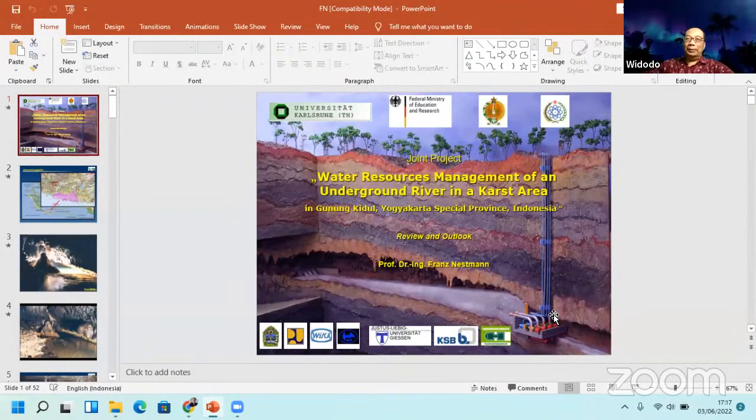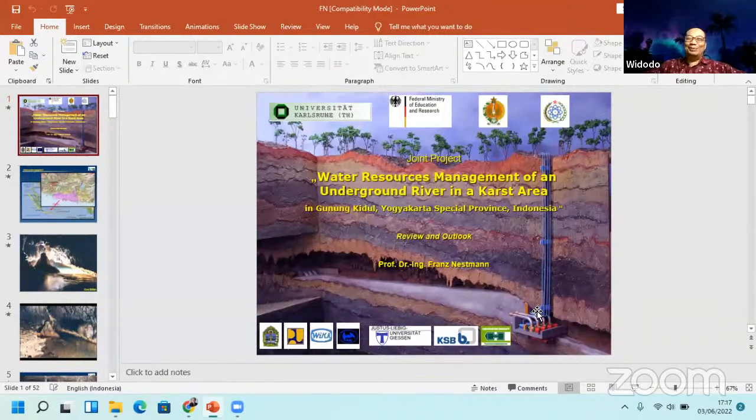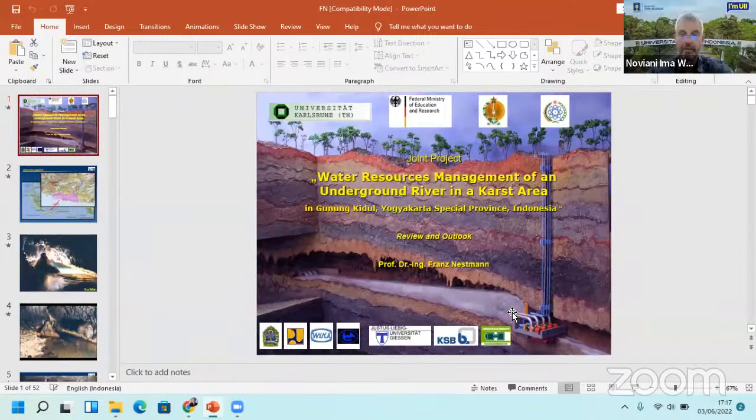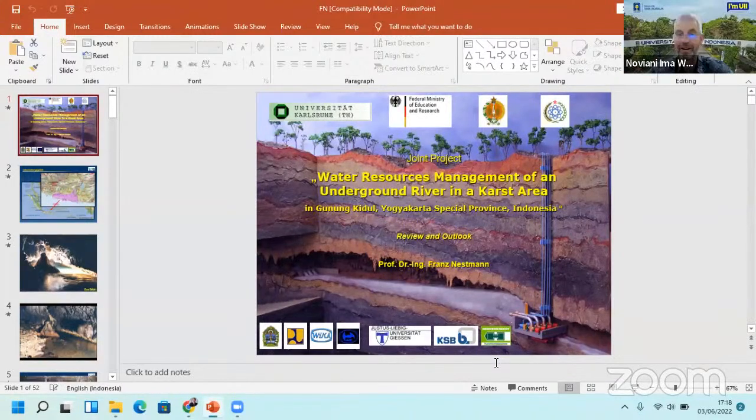Yeah, but another problem is the crack of the limestone, the karst here. So leak of the water is kind of leakage. Oh yeah, right. That's another. You have to basically, before you fill the cave, completely seal all the cracks with concrete or some rubber or whatever. Yeah, but it is big here. Yes, very big here. So complicated. Very difficult, and probably not going to be effective because you get one small earthquake and then you have even more cracks.